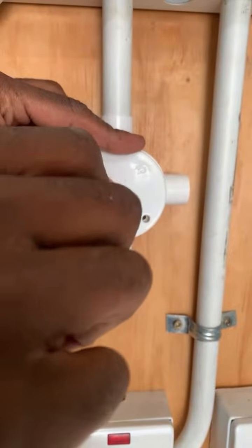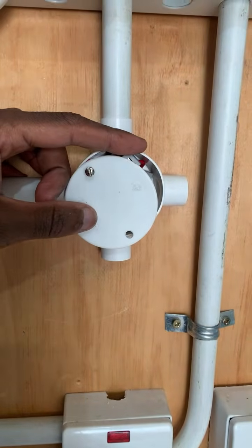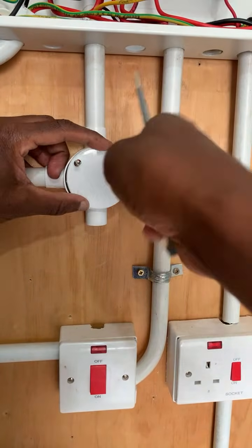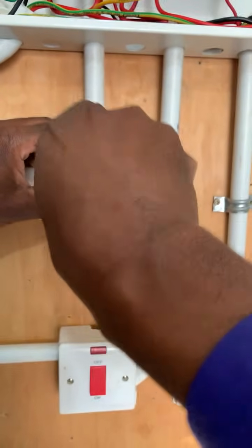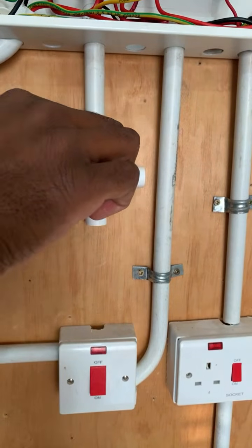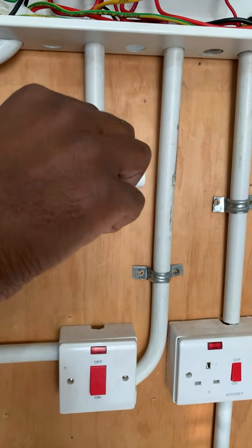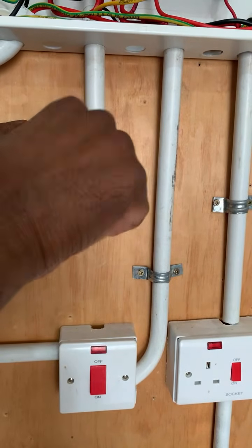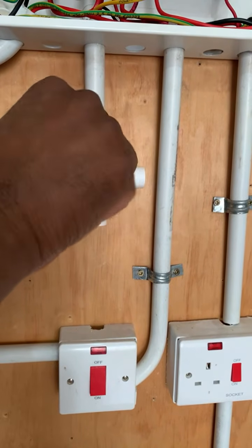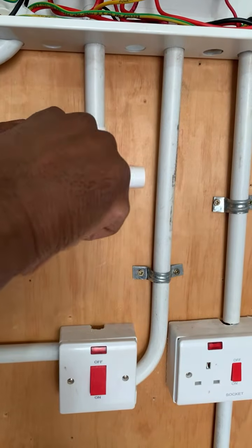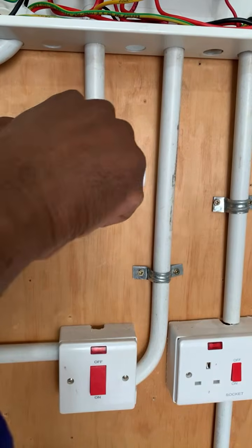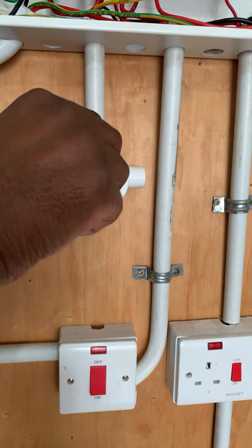But for this case, especially when it comes to making electrical connections or joints such as this one in the ceiling, or joints that will be in the slab, ensure that you definitely use the WAGO connectors. At least at the moment, WAGO connectors are so good.